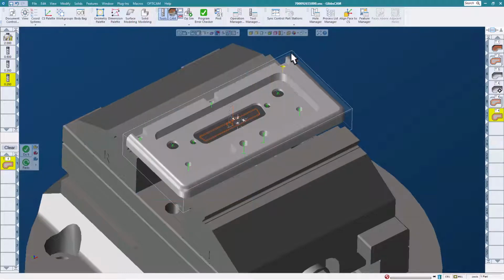Okay. So what we're going to do is use a macro to go ahead and machine a couple of these holes. You can also right mouse click on that when it's highlighted and grab the whole group. So at the bottom here we say group 3. And then I'm going to go up here and say go ahead and drill that for me. Now this particular macro has some stuff we put in there just so I can see what's going on. So in this case it says, hey, that's the size of the hole. And by the way, you're done, because it happens pretty fast. So we want to make sure that we're getting all the things we're getting.